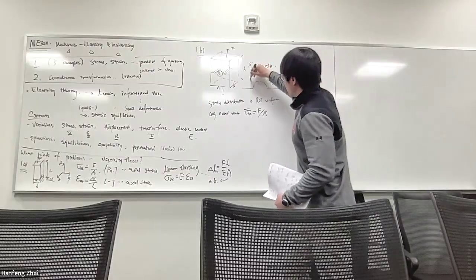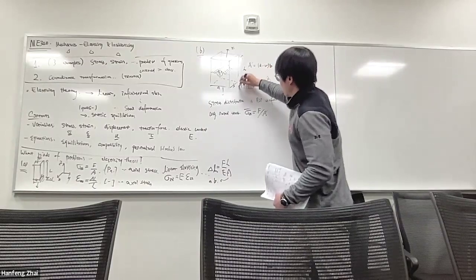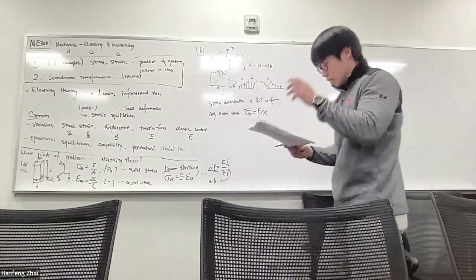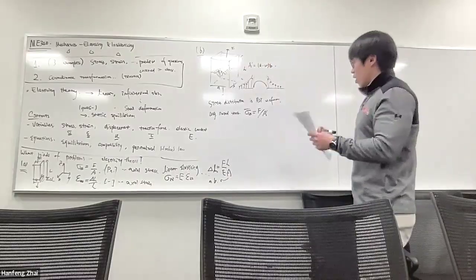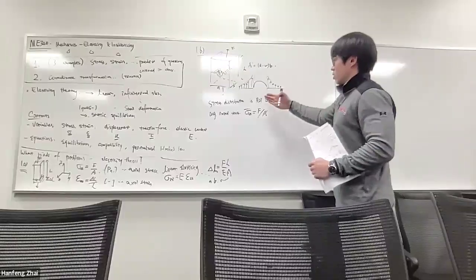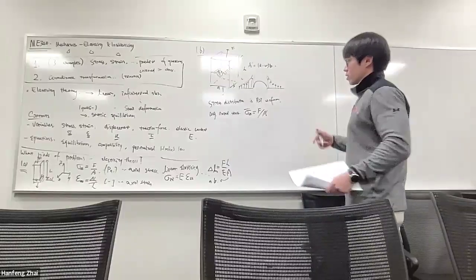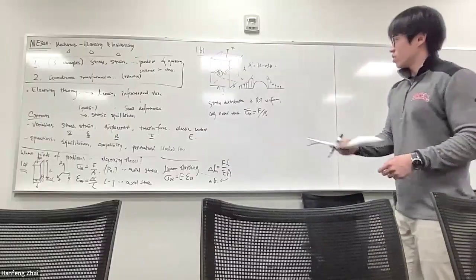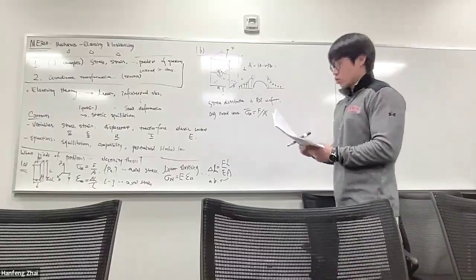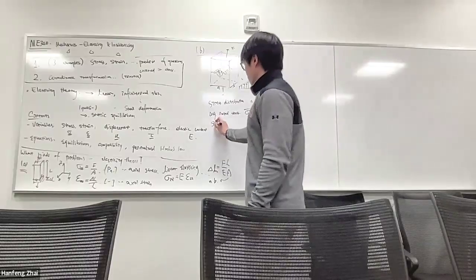And the same here, if the cylindrical hole is in the center of the material. So how do we characterize or mathematically describe this stress variance? One way to describe this is we introduce a concept called the stress concentration factor.